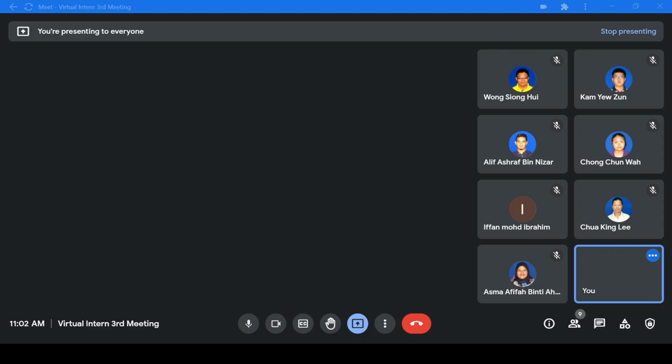Both are creating the same clock signal. All right, but if you have this, clock equal to 1, you start with 1, it means that your clock will be like this. Instead of starting from 0 at time 0 here, it will start with 1 for 10 nanosecond and go back to 0 at 10 nanosecond.